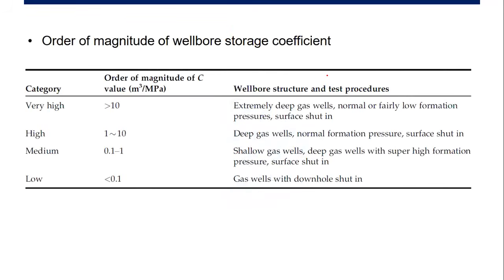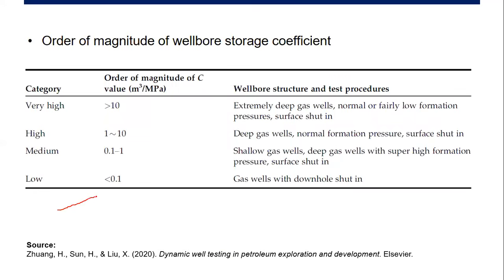All right, we know wellbore storage and the order of magnitude of wellbore storage. In this case for gas wells, you can see in this table. We have very high wellbore storage coefficient if the value is greater than 10 meter cube per megapascal. And we can read it together.